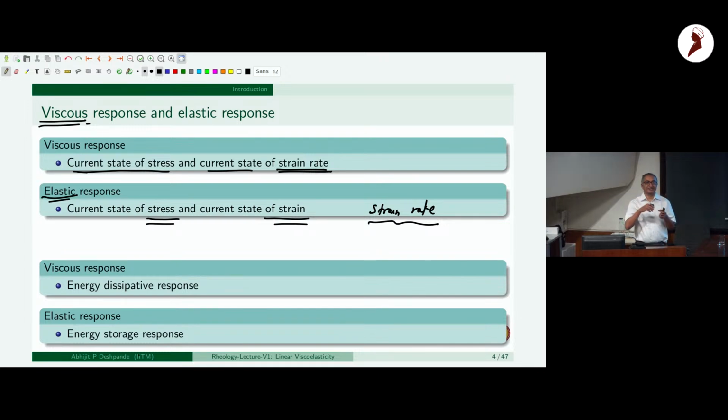Looking at a perfectly crystalline solid, one is only saying that the unit cell has been deformed, and the relative displacement between atoms, the way it has changed, only that determines the energy, and that's what gets translated to the stress. So stress and strain are related to each other purely based on this idea of configuration-dependent energy, and that is basically the internal energy of the system.